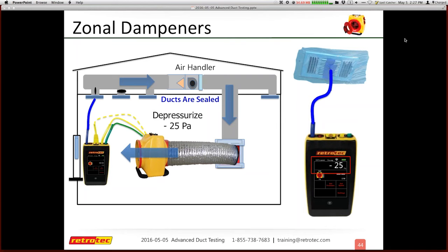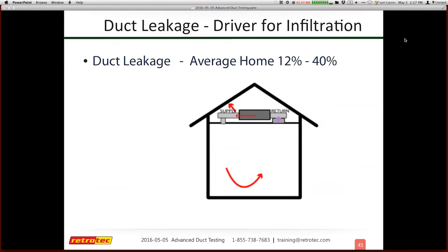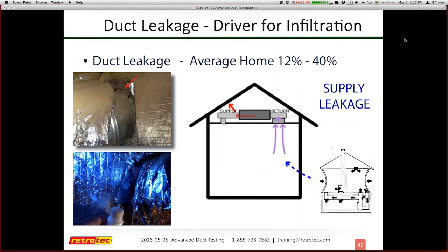I work with a bunch of folks in California, and it doesn't depend on area. It depends on either the mechanical system or how the engineer or the HVAC guy has actually set it up. So it's not a given that they're always open. If you're not sure or you feel like you're getting funky readings, sometimes one zone can control multiple duct runs, or there can be individual controls over each run. So you want to make sure you're getting pressures throughout your system.